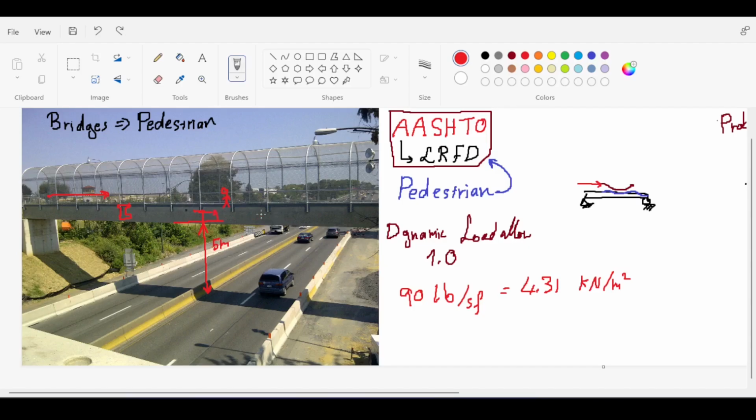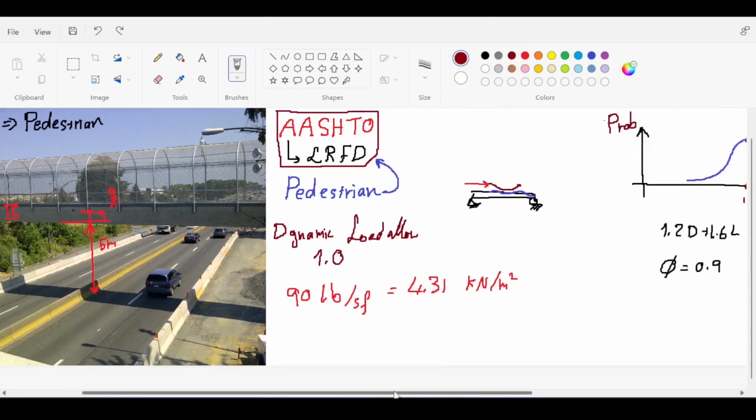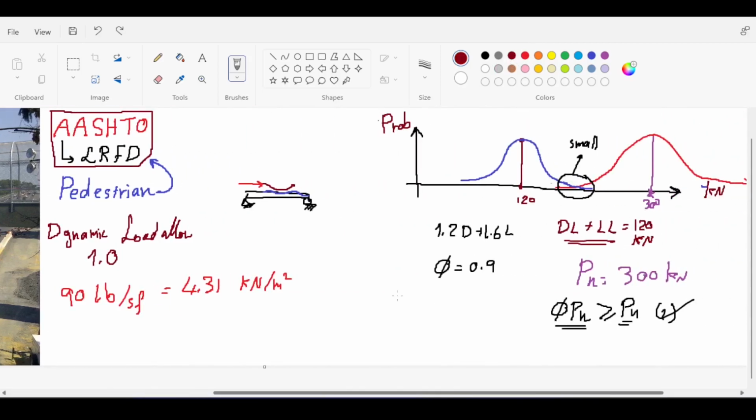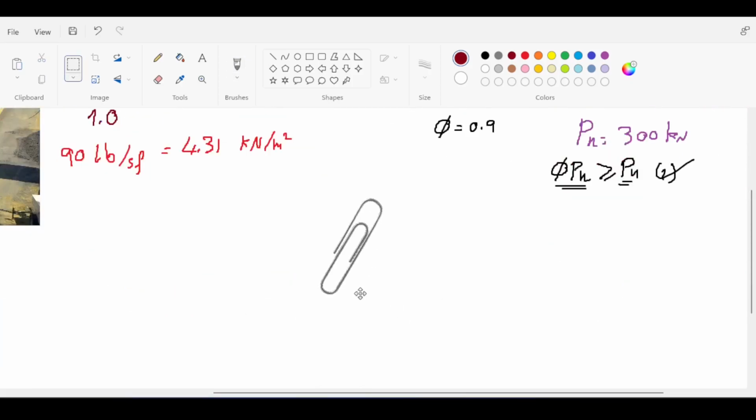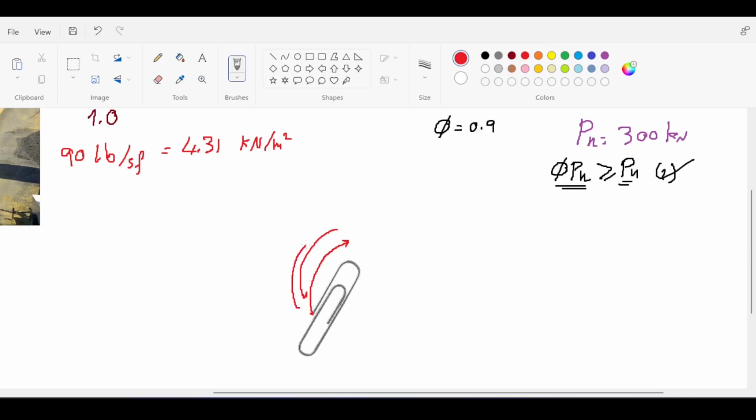What about fatigue loads? Well, what is fatigue? I want to define it in a very simple way. Fatigue is the loss of strength under cyclic loading. The simplest way of talking about fatigue is talking about a paperclip like this, the paperclip that everybody uses in daily life. So how would I break this paperclip? I will just take this edge, get it out, get it back in, and keep repeating this cycle of bending it out and in, back and forth, multiple times until it finally breaks here.